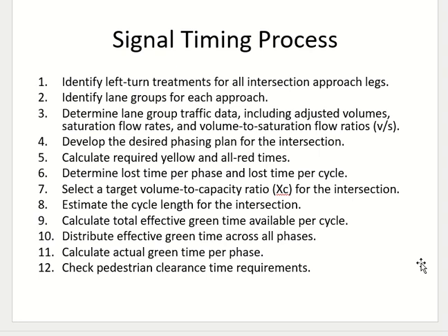What is the phase? Not green phase, yellow phase, or red phase. Those are intervals. What is the phase? It is from green to orange, from green to all red. Good. From green to all red. Every direction has this. So that is the phase, and then we have the whole cycle, which is the summation of the phases.